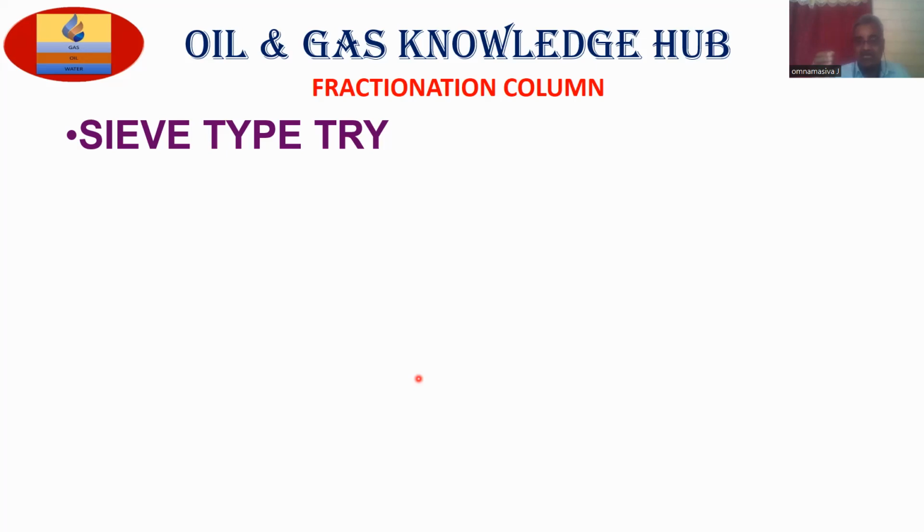Just the basic important point about materials I am telling you. Remember, all columns will be designed based on sour or sweet service. Based on that, they will select the material. For example, you can say P9 material or LTCS material. Like this, you can give the answer. And for any internals, it may be wall cladding, column cladding, or trays, girders, which are used in the internal process area at different elevated temperatures, 400 series construction material will be used.